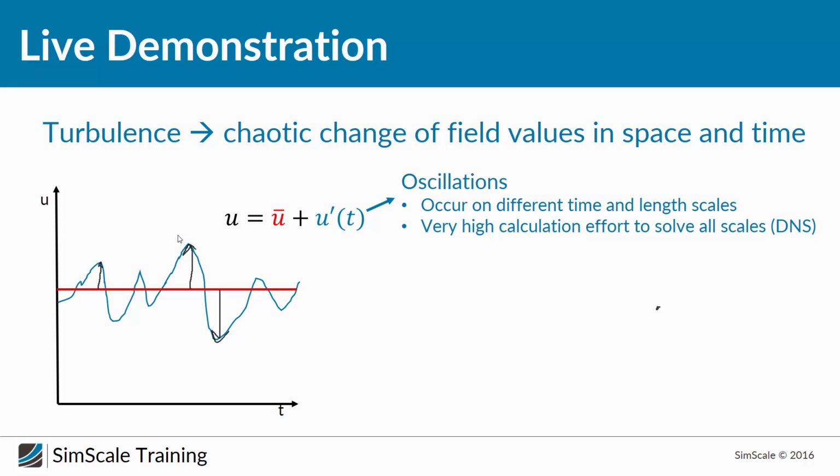And remember how CFD is working, that we try to numerically solve the Navier-Stokes equations. That will be a high effort, because if you really would like to solve turbulence based on the Navier-Stokes equations like this, you would have an incredibly high effort to solve all scales, which would mean if you have a very, very small time scale, like let's say 1 nanosecond, here in this graph, you have to use a time step of 1 nanosecond. And then you can imagine how many time steps you have.